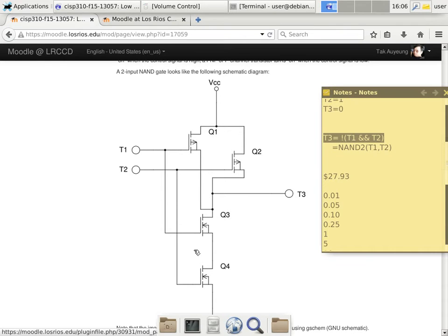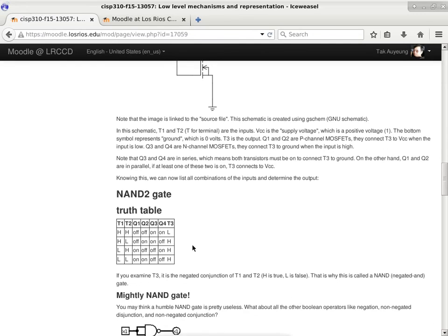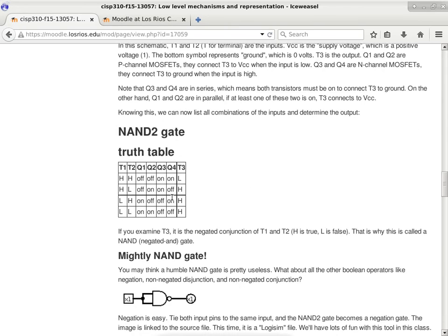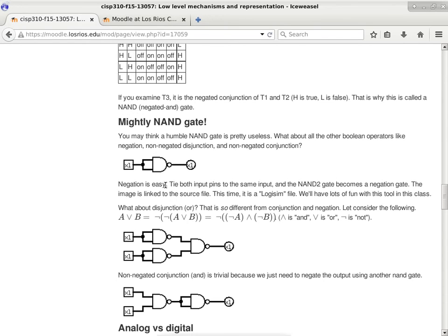All right. So the next thing that we talked about the other day, and I know the font is really small, but that's kind of okay for now because I just want to show you the diagram. So the other thing that we talked about is, okay, this is a kind of weird little construct. It's called a negated AND gate. So why not a regular AND or regular NOT or OR? Well, we can make all of those things out of a NAND gate.